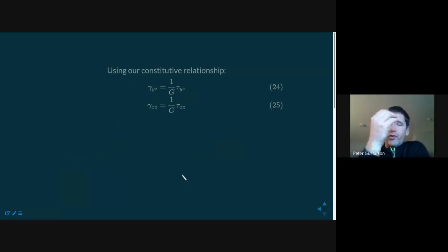Okay, now separately, let me just check some boxes here first. If you recall what we said we needed to do with elasticity theory, there was that chain of relationships that needed to functionally work. So we had a displacement field, through strain kinematics gave us a strain, through the constitutive law gave us a stress, and the stress through the Cauchy equation and the definition of the traction meets the traction boundary conditions.